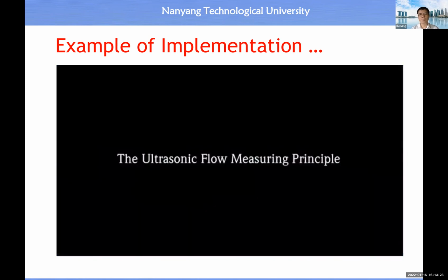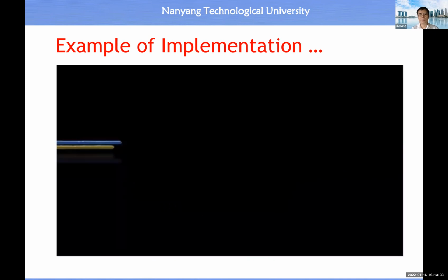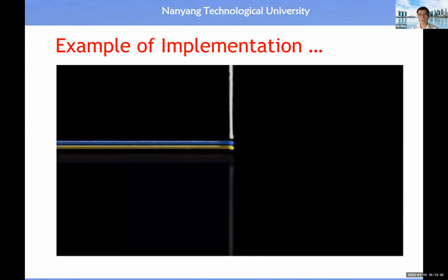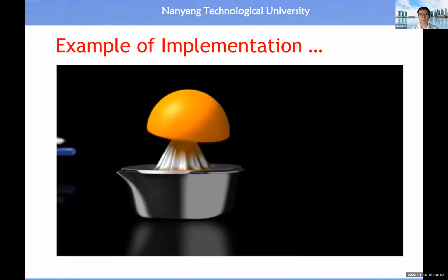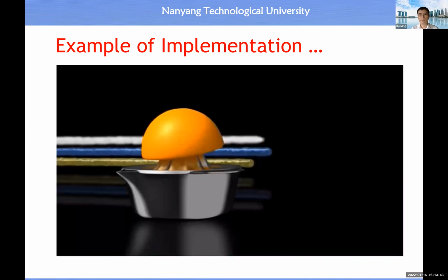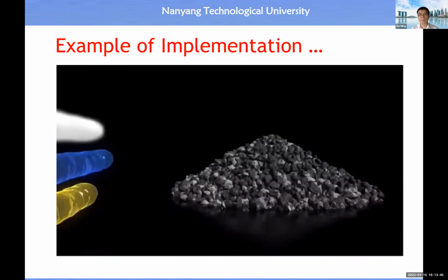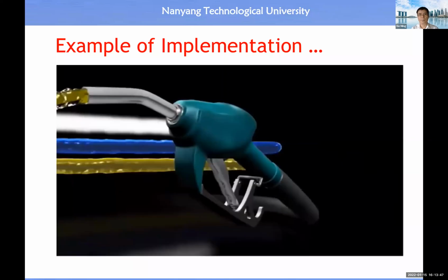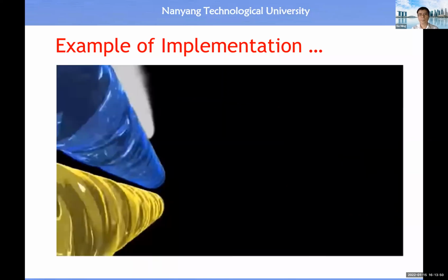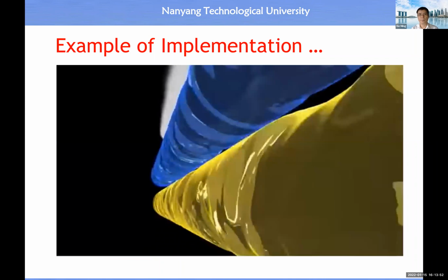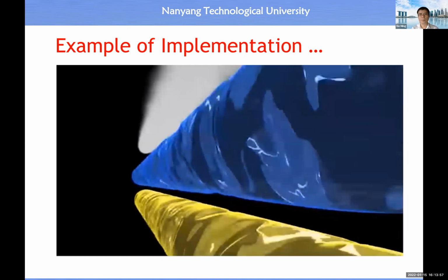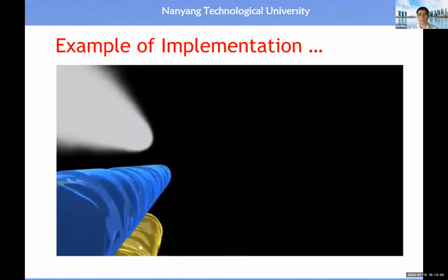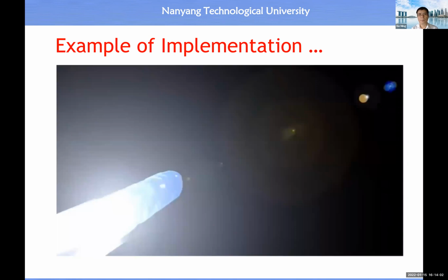The most diverse substances are transported and distributed in piping systems every single day. They can include solvents and chemicals, vegetable oils in the food sector, coolants in primary industry, or petrochemical products. The fluids flowing through pipes often have completely different properties. Therefore, different principles are required for their measurement. One principle is flow measurement based on the differential transit time method using ultrasound.